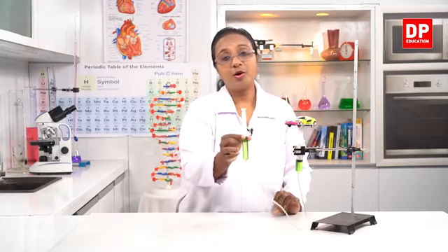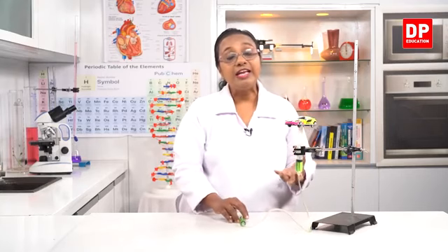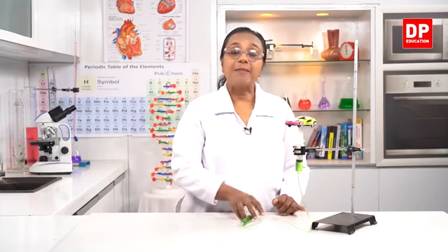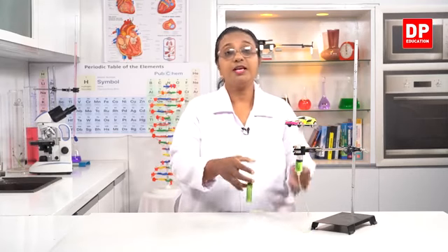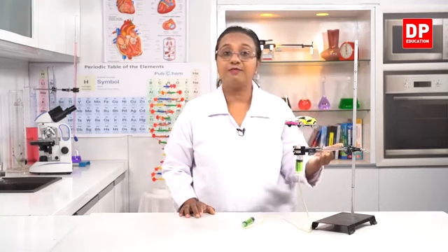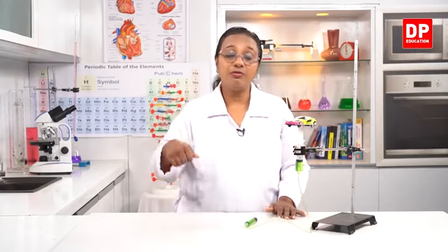But here students, you all have to remember, now this is a toy car, so a small amount of water was enough to hoist it up. But for a real car, the weight of the car is more. So to apply that amount of pressure by applying a force to the small piston, we transmit the pressure, but we need a higher force acting upward so that the car, the real car or any vehicle for that matter, will be hoisted up. So to do that, it is difficult to press the small piston, because then you will need to have a very tall liquid column inside the small piston and you have to keep on pressing it